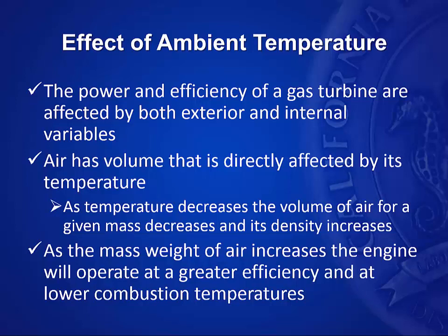Because of that increased air temperature, that air being drawn in will be at a lot less volume, or density, it will be less dense coming in. So that will affect and drop down the mass flow air rate. The other thing about this is within the